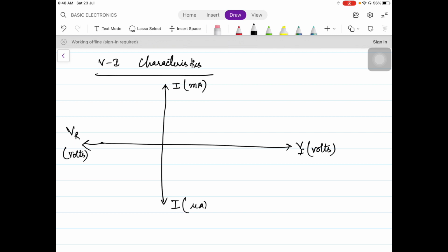All right. Now, let us see the case of forward biasing. We already told that, for example, this is the potential barrier or the knee voltage: 0.7 volt for silicon, 0.3 volt for germanium. Till the knee voltage, current will be negligible. But as soon as the battery value, this particular voltage, exceeds the potential barrier, the current will rise rapidly. All right, so this is the case for forward biasing, and that's all for forward biasing.